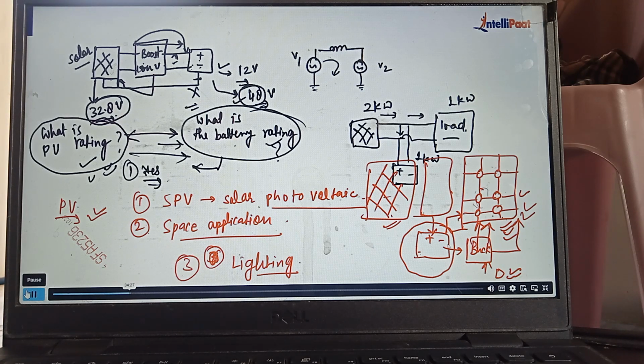So what is the purpose of telling this? We can control the battery performance, because as soon as I control the duty cycle, I am controlling the voltage, and I am not wasting the battery power in these LEDs. Therefore, this way we are controlling the intensity of light, and we can successfully optimize the battery power. Similarly, for other performance, MPPT, maximum power point tracking, we can utilize here, and we can charge the batteries.